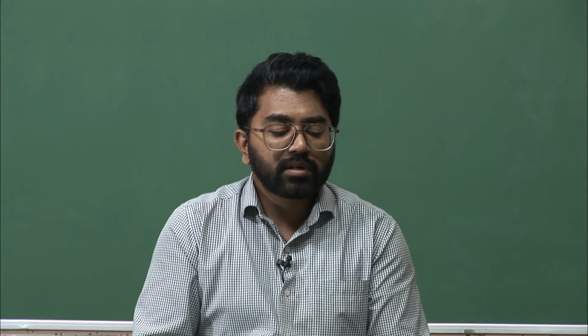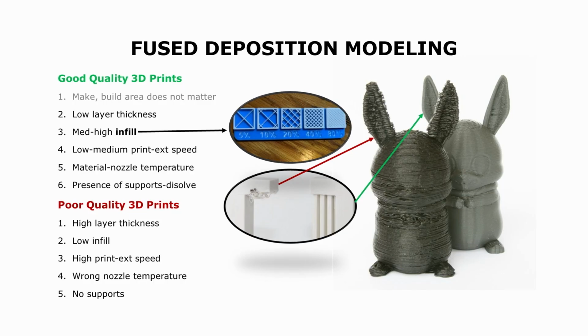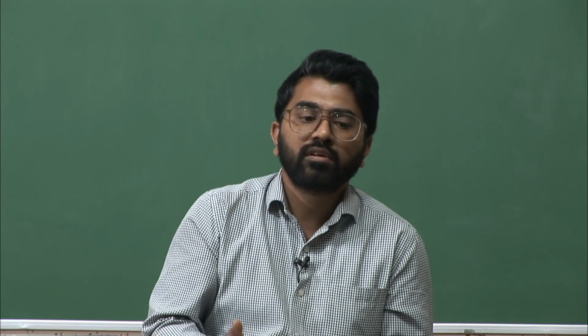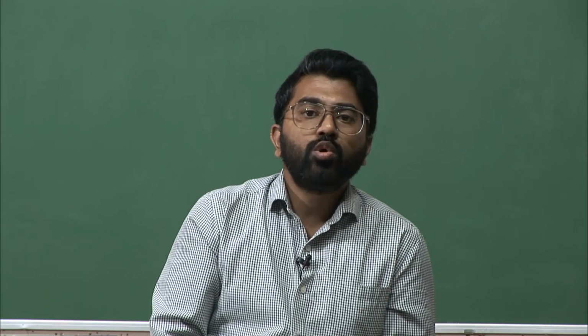Then you have something known as a poor quality 3D print. A poor quality 3D print has the characteristic of high layer thickness. If you have a very thick layer, it will typically give a very poor finish, and it's a poor quality print. Low infill.